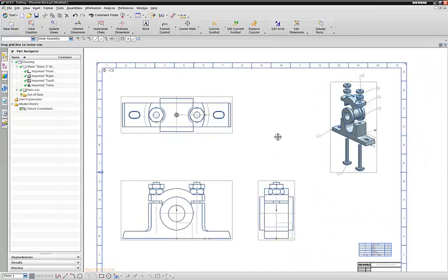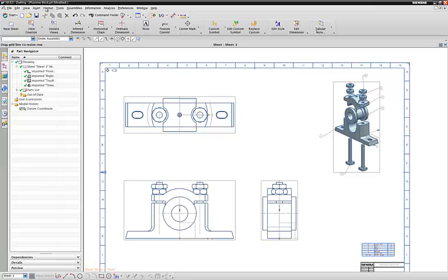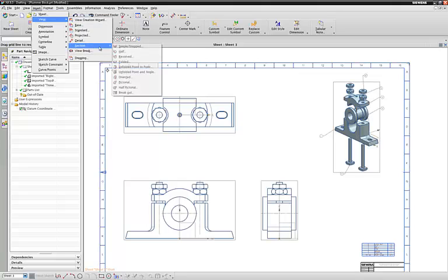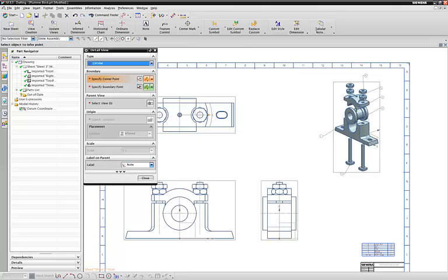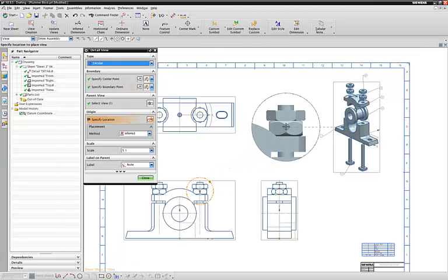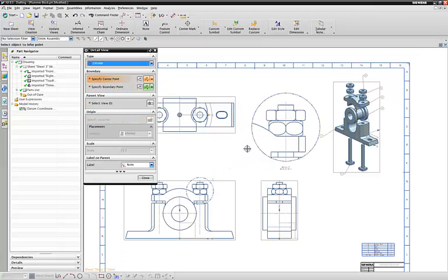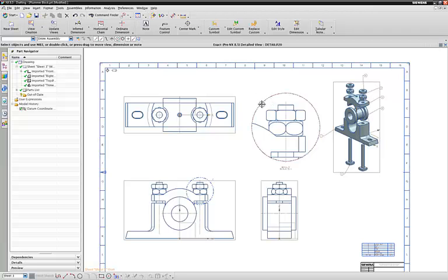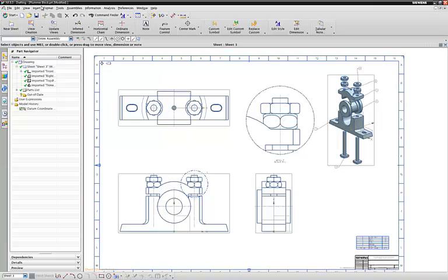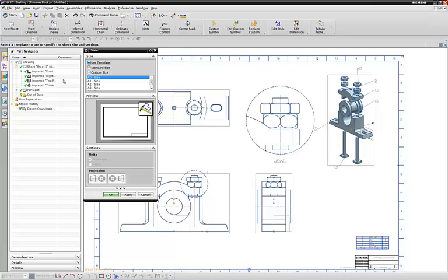So now that we have our table matched up with our assembly, we can do section views, or section views and detail views. We'll do a detail view first. So you just select and drag your circle around the object, and then you can place it. That way you have a bigger view of what you're looking at for complicated parts or locations that have lots of detail in them. We're going to create a new sheet now for that cylinder because it has a tricky piece on it. So we're going to do the same thing.